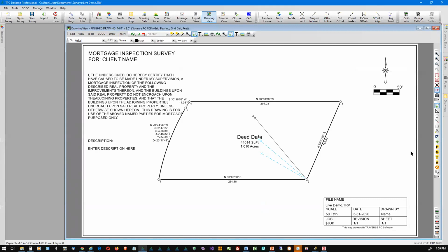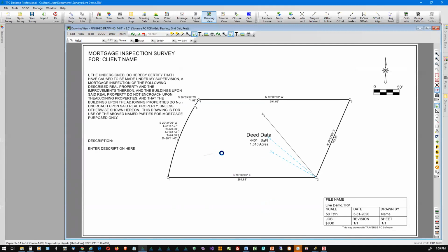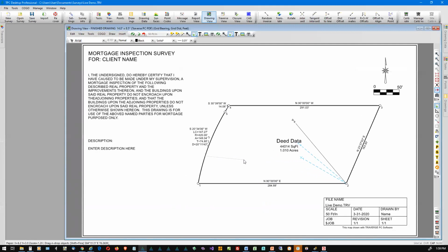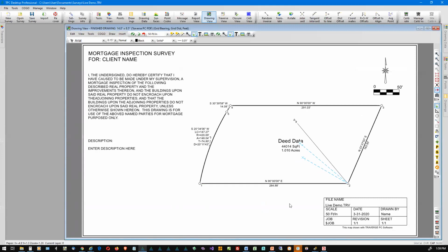So now I want more room over here for my notes. I can do a control drag and drop in the background. Watching the status bar, see the status bar down here. Watch down in this area. See survey, press the control key to drag survey. Depending on what your cursor is on will determine what's down there. So if I'm on this, it doesn't say that. Now if I drag and drop, I'm dragging and dropping that label. If my cursor is here, it says press the control key to drag survey.